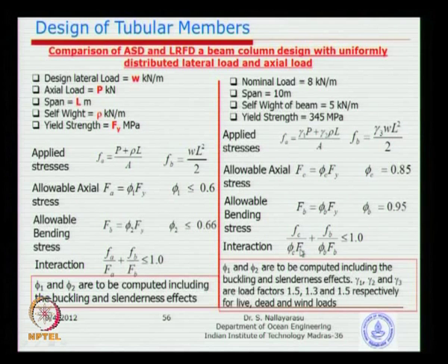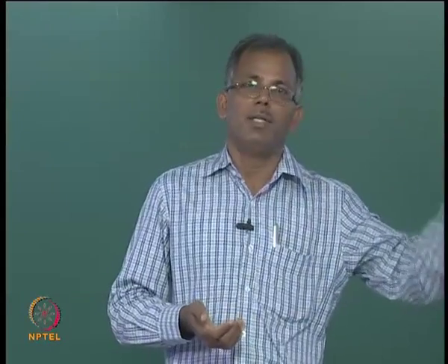You see here phi c is taken there. So, I think in summary the design method does not change, mechanics does not change, only the treatment of variables like loading or the resistance are treated in a better way. So, in my opinion you cannot get a different result when you design by allowable stress method or LRFD method. The variation of design result could only be a very small magnitude. So, you cannot get wonders whether I design by LRFD or the allowable stress method. You could only fine tune the design, but not find a new design.